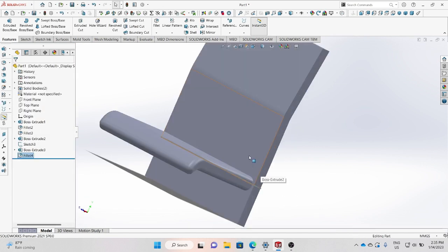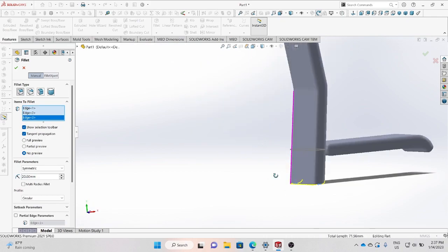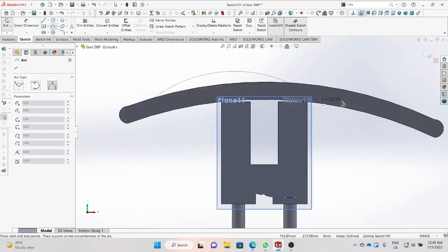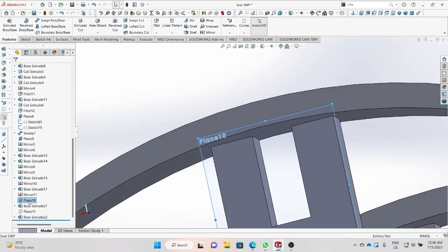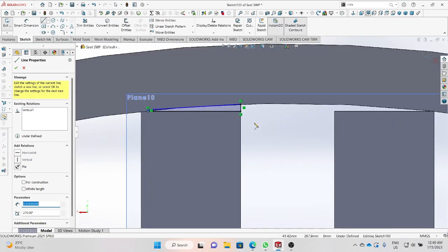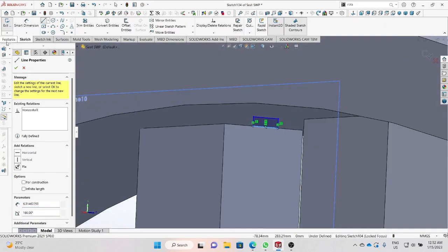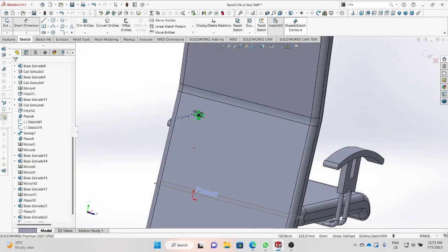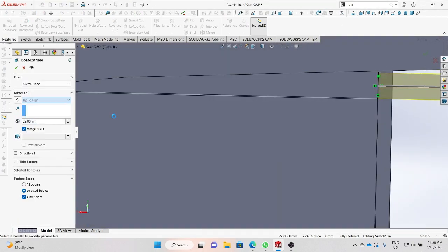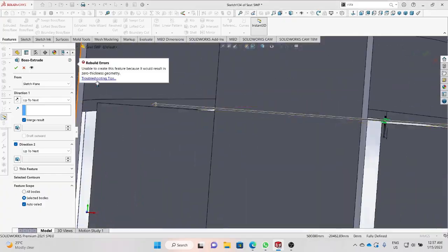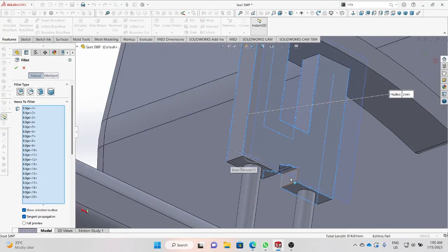Next, you can click sketch on the right plane again and set the height to 650mm and width 65mm. And then click exit sketch and extruded boss, set it to 500mm and click the tick symbol. And lastly, for the backrest on the bottom, we also sketch from the right plane and set the width to 65mm and the height to 180mm.